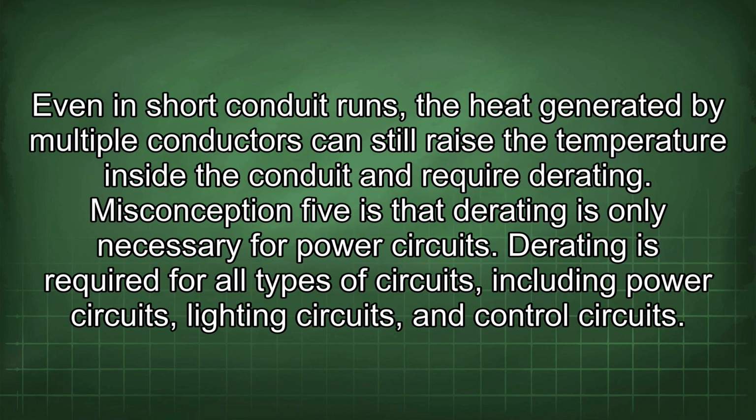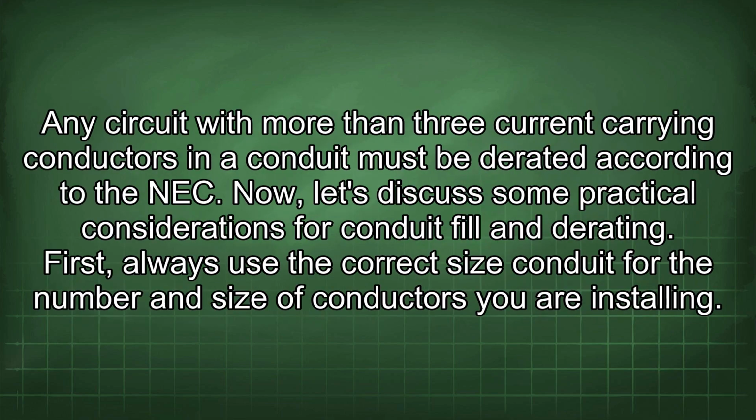Even in short conduit runs, the heat generated by multiple conductors can still raise the temperature inside the conduit and require derating. Misconception 5 is that derating is only necessary for power circuits. Derating is required for all types of circuits, including power circuits, lighting circuits, and control circuits. Any circuit with more than 3 current-carrying conductors in a conduit must be derated according to the NEC.